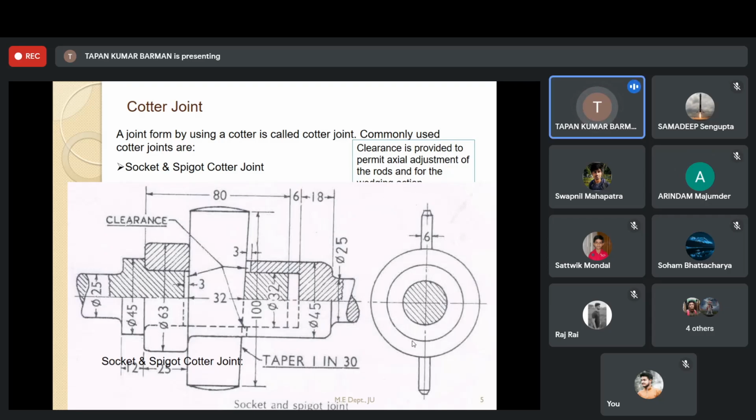So two components you may identify easily. That is this one, and another component this one, because the hatch patterns here are different. So by identifying the hatch patterns, you may identify the components. Also at the middle you can see another component. This is a third component, but it is not hatched, there is no section line.